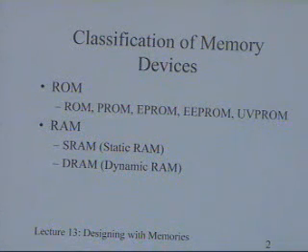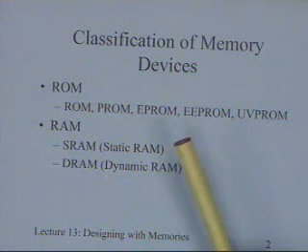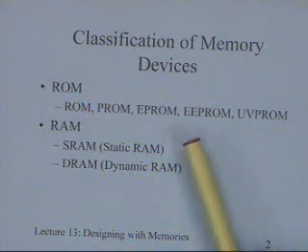You can say that they are no longer read-only memory because you can also erase them and rewrite them. Fundamentally the way they differ is in terms of the erasing circuitry required, even sometimes the voltages required, and the timing required is not the same as the timing required for reading.